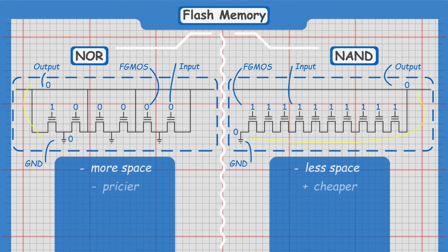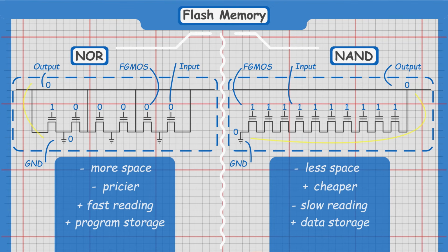Therefore, NAND is cheaper. On the other hand, NOR memory needs less time to read a bit because of its direct access to individual cells. It also makes random access possible, allowing NOR flash to be used for program storage and NAND flash for systems with a need for high-capacity data storage. When looking at programming and erasure performance of both, it turns out that because of its smaller cost and space usage, NAND flash can justify being structured in pricier, smaller blocks. And smaller blocks mean less time is required to erase data.